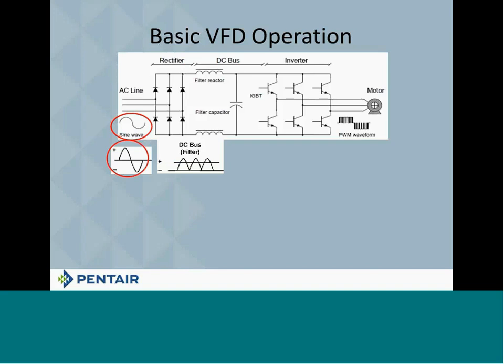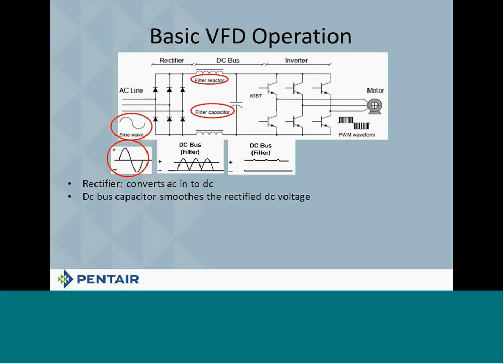Then what it does is it runs it through a set of capacitors. And as it goes through those capacitors, they bring it fine line down to what we call DC current. Remember, DC current is running in one direction and one direction only. There's no more AC here. Okay? So we take it, we run it through our DC bus, our filter, and that's our capacitors, and that brings it down to a straight line. We get that flat line to run into what we call IGBT switches.